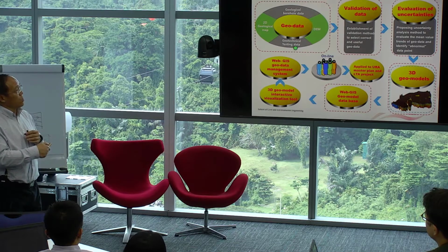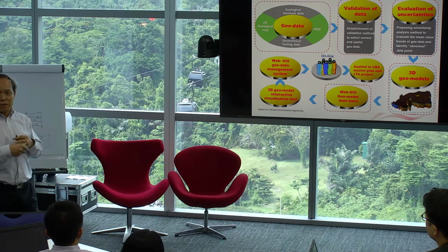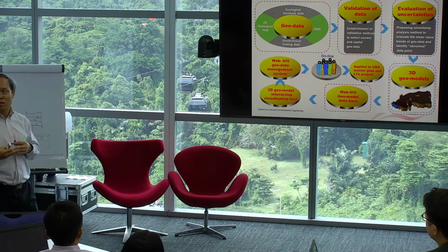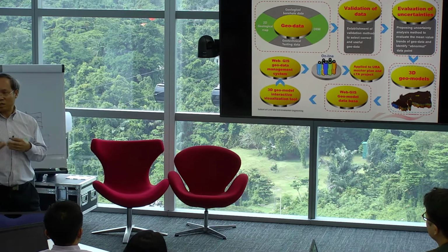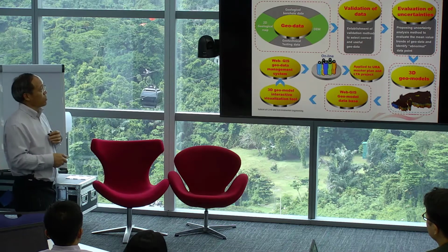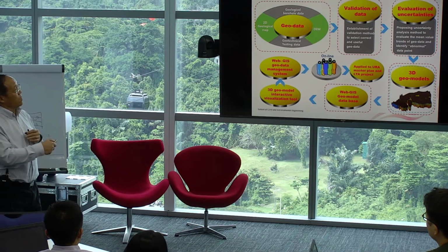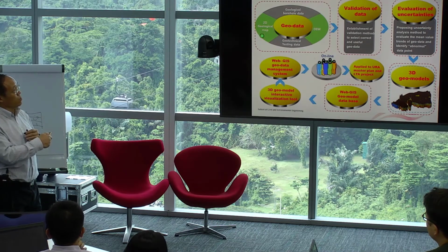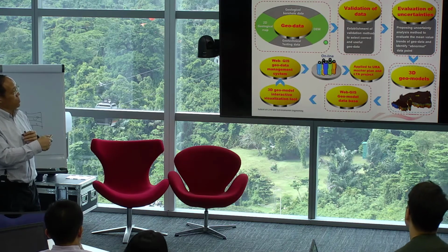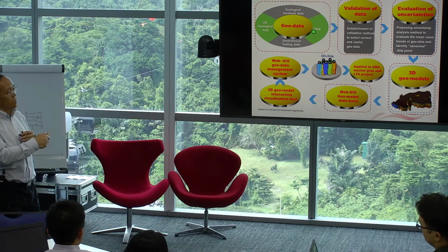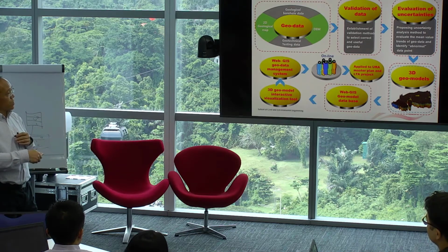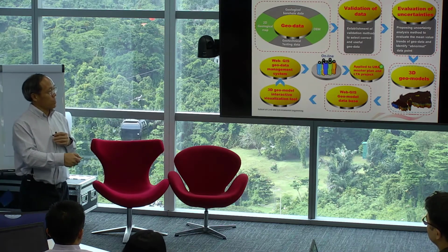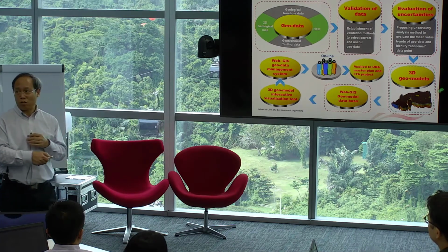In the same database, there are also geotechnical testing data, for example, SPT and in situ testing, as well as some laboratory testing data. We need to make use of the 2D geological map, which you have just seen, combined with the DEM, which is the elevation. By putting them together, we can construct the 3D geological model.